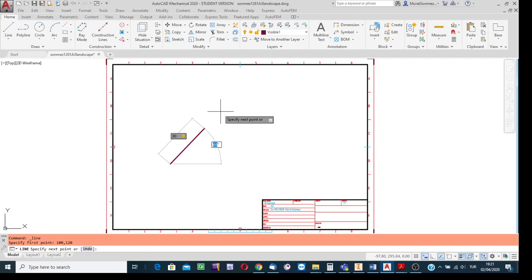If yes, then write the number to its absolute value always. Say that in our example, the angle of the line is 35 degrees. No need to write degree because AutoCAD considers that number in degrees. Okay. And then the rest. Press enter. That is it. The created line is the corresponding output. Its length is 80, inclination angle is 35 degrees.